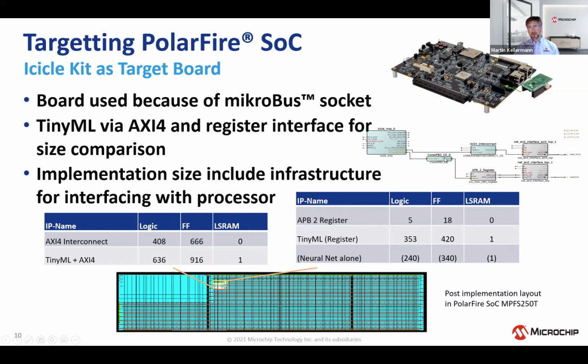Here, the register interface, the conversion here from the MSS into the fabric, then the conversion, which is also just a bit of C code, a couple of lines of C code where I was taking the data from here, and then driving an 8-bit interface or a couple of 8-bit interfaces, and those are then going into the simple instantiation of the deep net.